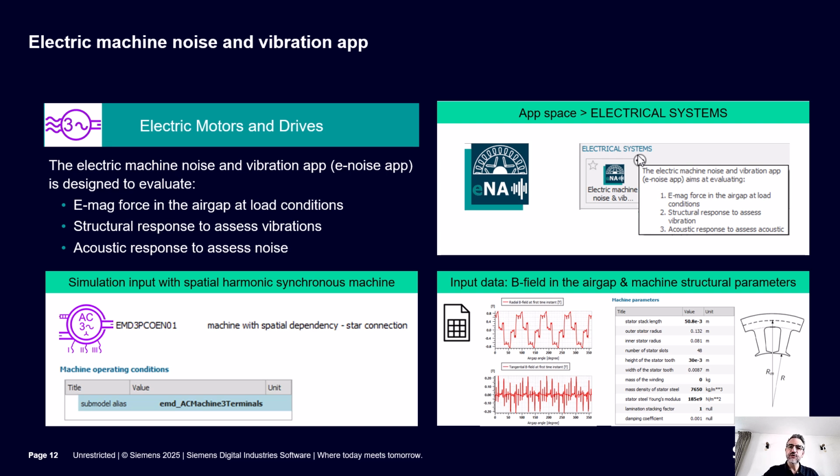We will then use some basic assumptions about the structural parameters of the electric machine in order to be able to predict the noise radiated from these electromagnetic excitations. So here we see, for instance, some assumptions which we do about the geometry. And this will allow us to predict the vibration, and then we will make a free field assumption to have a quantification of the noise level from the e-machine from the very early stage of the design.